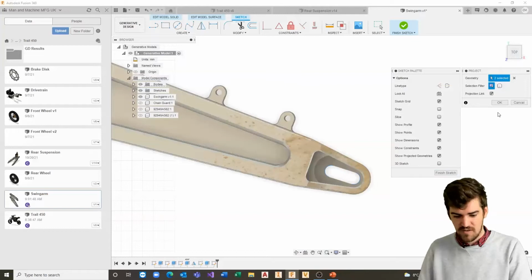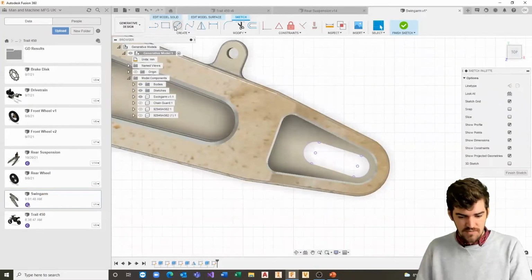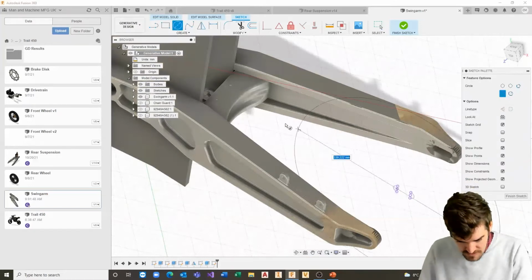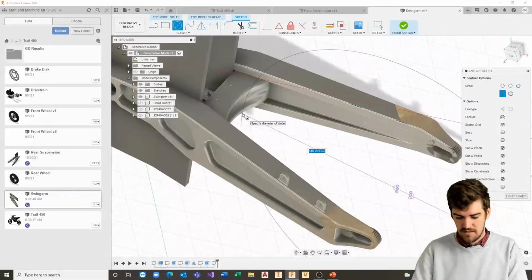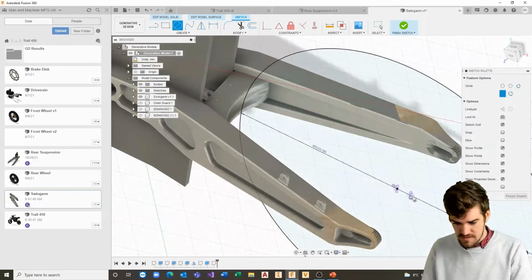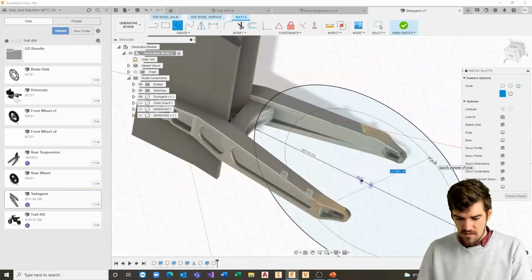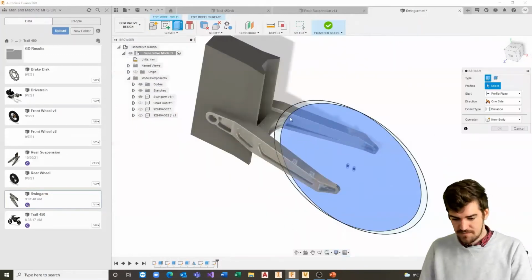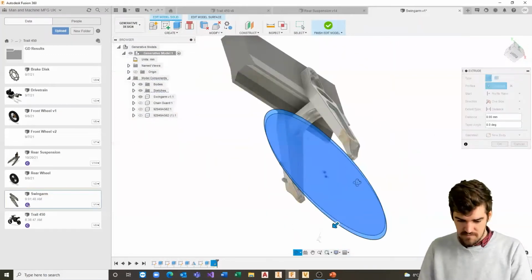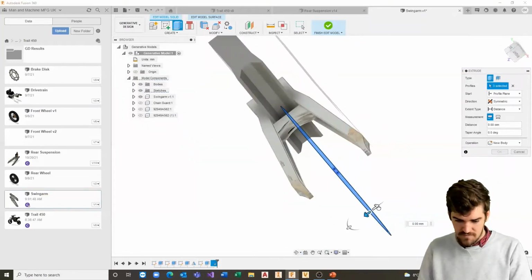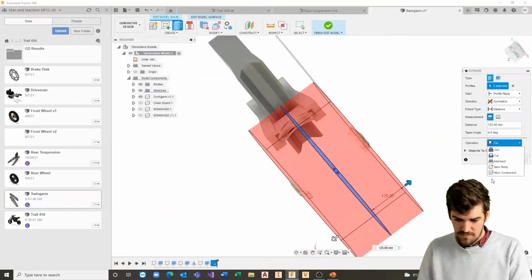So if I finish that projection, we're going to make that more or less 520 millimeters from both of the centers. I'll then quickly create an extrusion, this time a symmetrical one, and create it as a new body.